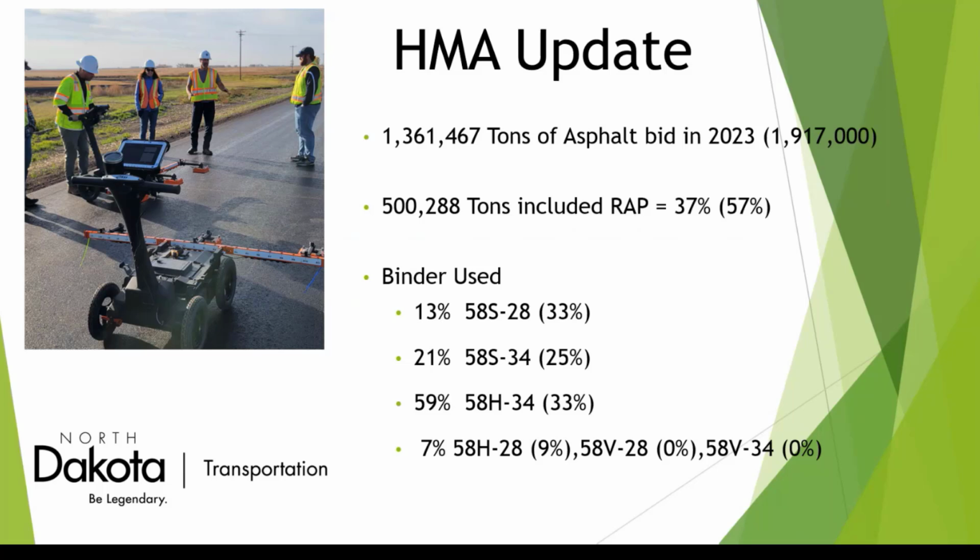That's the typical base grade asphalt, almost always, I think, in North Dakota, non-modified, neat asphalt in terms of the trade. And now you're getting a lot more. The other transition has been to the -34, which I think is a good move by North Dakota.